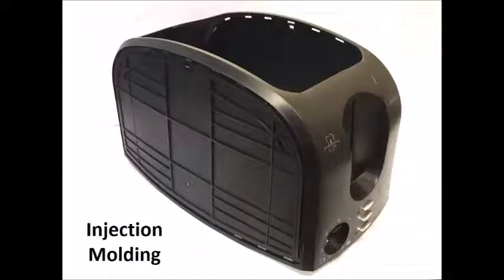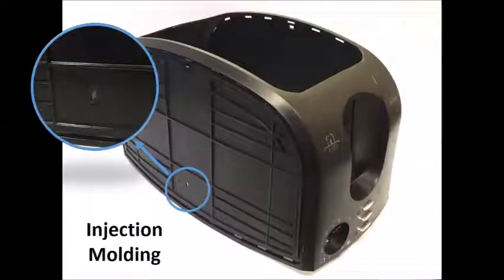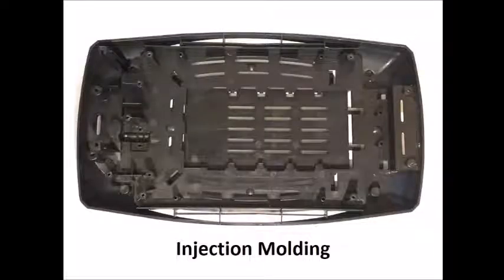Our first component is the case for the toaster. This was probably made by injection molding with a complex die. We think this because you can see the parting lines inside of the component. There is also a small hole in the part which is due to the lack of material used during injection molding. The next component is the bottom tray.